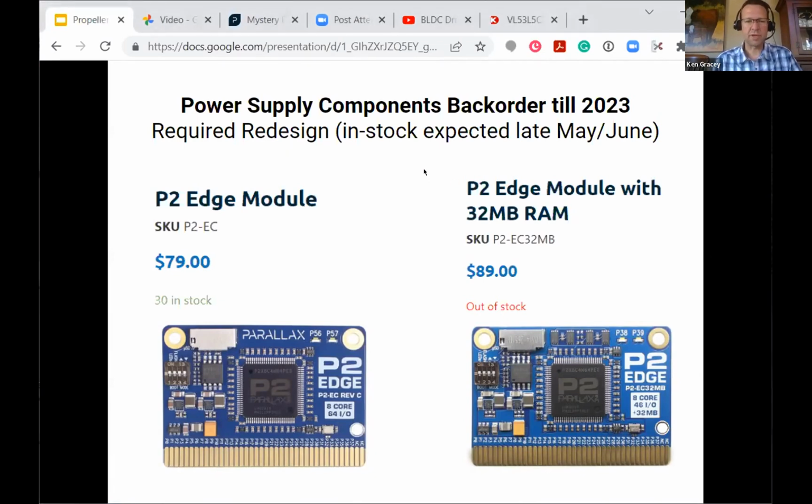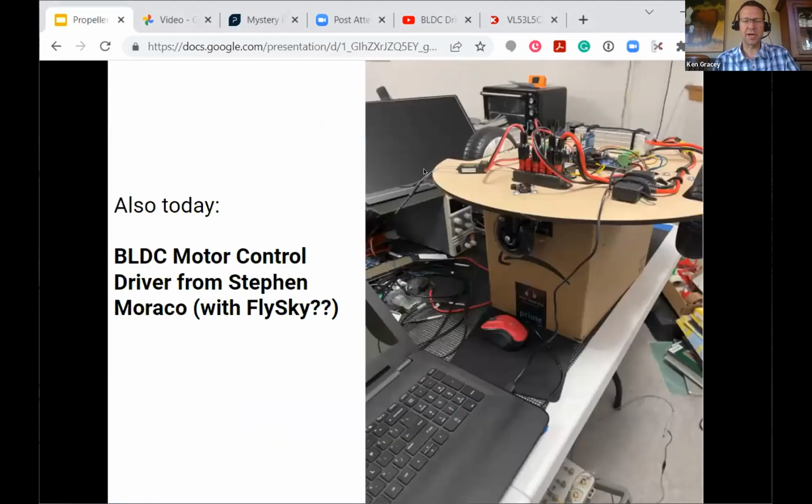Okay, so we have a video from Stephen to show. Just so everyone's up to speed on what we're doing with this. Chip's been working with the BLDC, the brushless motor, the hoverboard motors for quite some time. And then we made the motor driver board, and Michael, Chip, and Doug worked on that for a long time. We started it well over a year ago. And it's not perfect. We need to make some improvements to it, but we can run it reliably up to certain voltages, 18 volts with the hoverboard motors, and move things pretty darn fast.